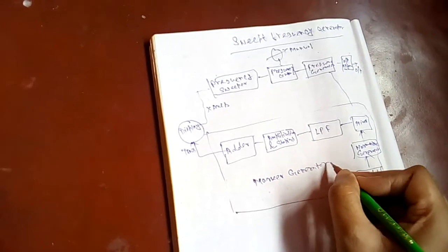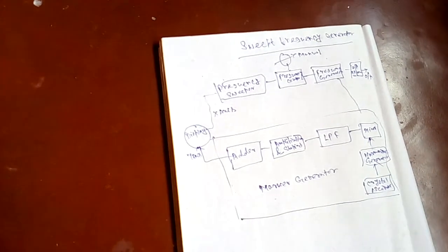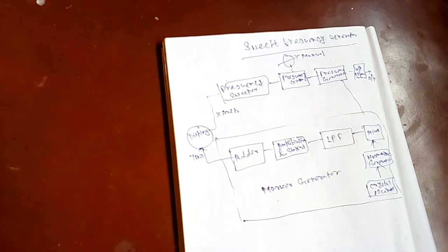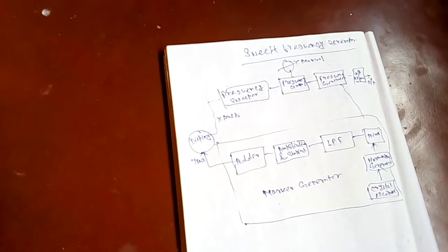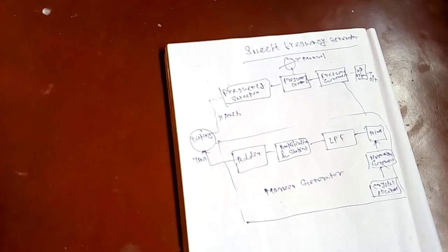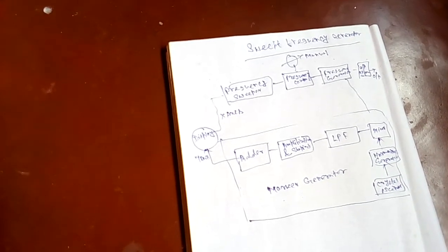From the block diagram, two modes are used for the frequency range. The first is the start and stop frequency mode, meaning F1 to F2. In this mode, the stop and start frequencies are set on the front panel, and the instrument sweeps between the limits.